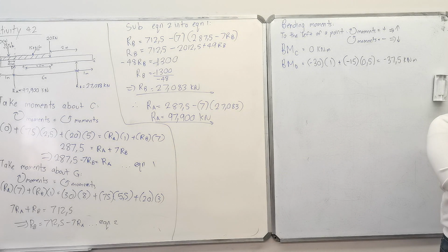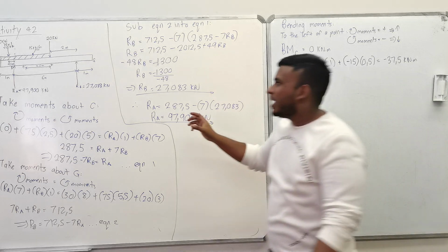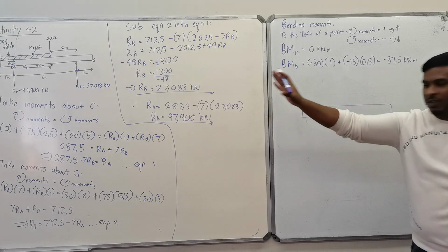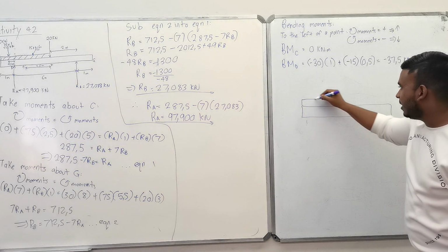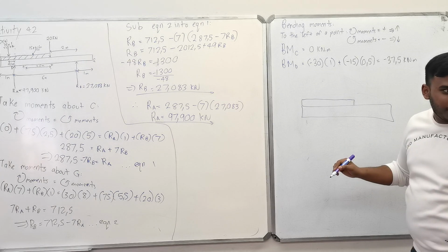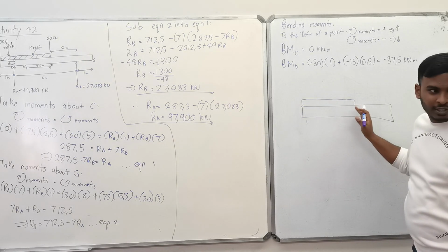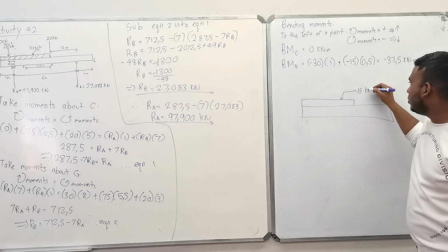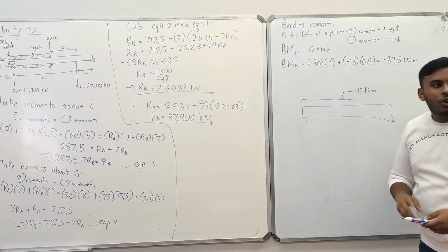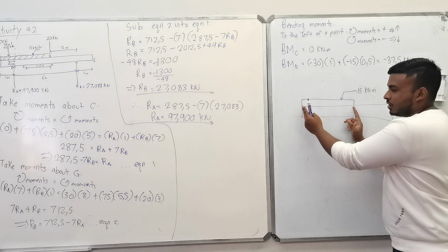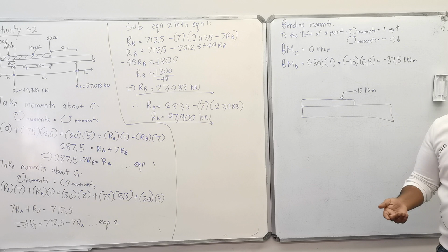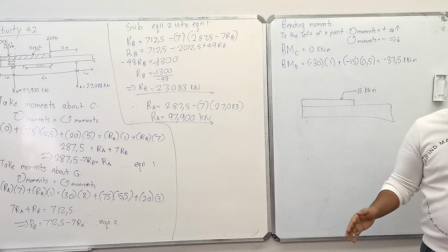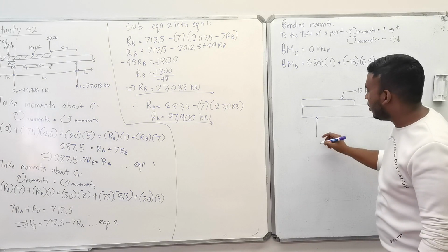Cindy, I feel like you never listened to me in this first part. See, say this was your beam, right? Same thing as there, I'm just showing it here without all the other stuff. And if this was the entire length of the beam, the uniformly distributed load, this was 5 meters, and they tell you it has a magnitude of 15 kilonewtons per meter. Normally, for the entire length of the distributed load, we get an average value, which is how we convert it into a concentrated load. We take this and multiply by the full length. But now you see you have the support that's acting here.